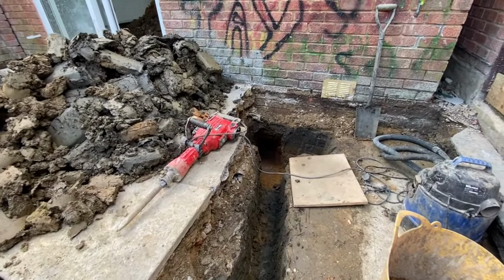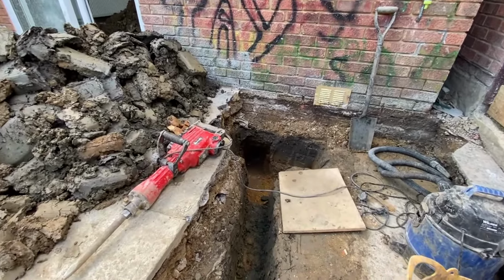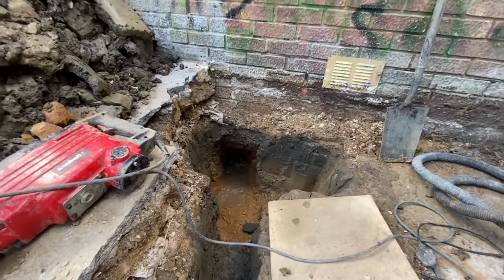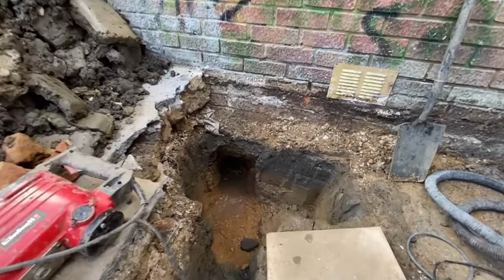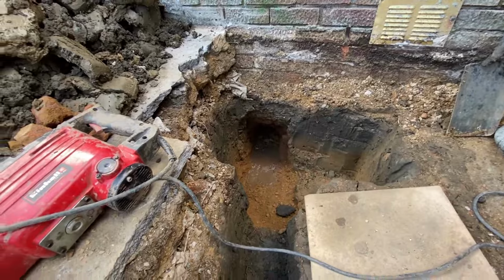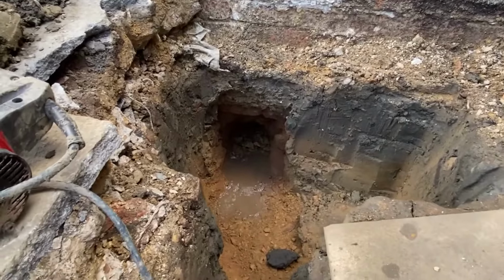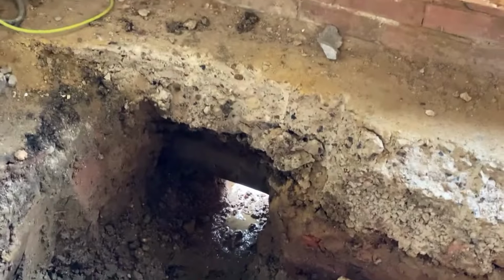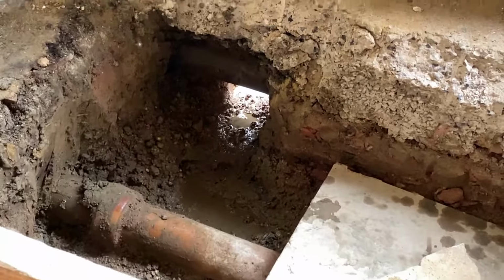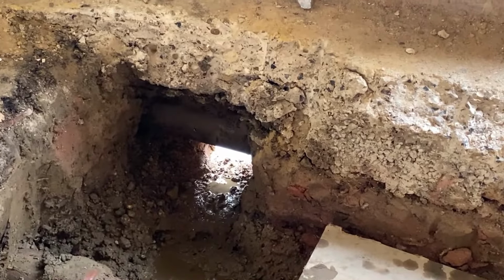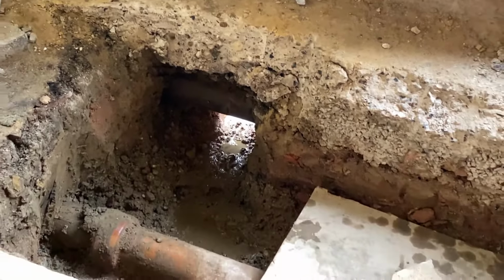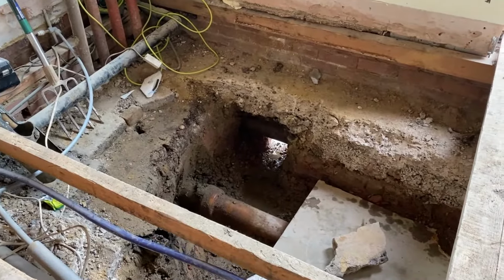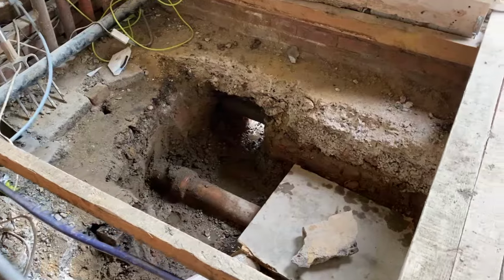But you can see we've dug down at the same level as the sewer pipe that you've seen internally, and we've now broken through the wall, so we've got a nice tunnel to be able to pass that pipe out of. So everything is now ready for us to start doing the actual laying of the pipework. And here's the same view from the other side, from internally. So you can see where the sewer pipe is at the bottom, and then there's the nice gap there for us to be able to join the rodding access and connect up the new drainage system for the house.